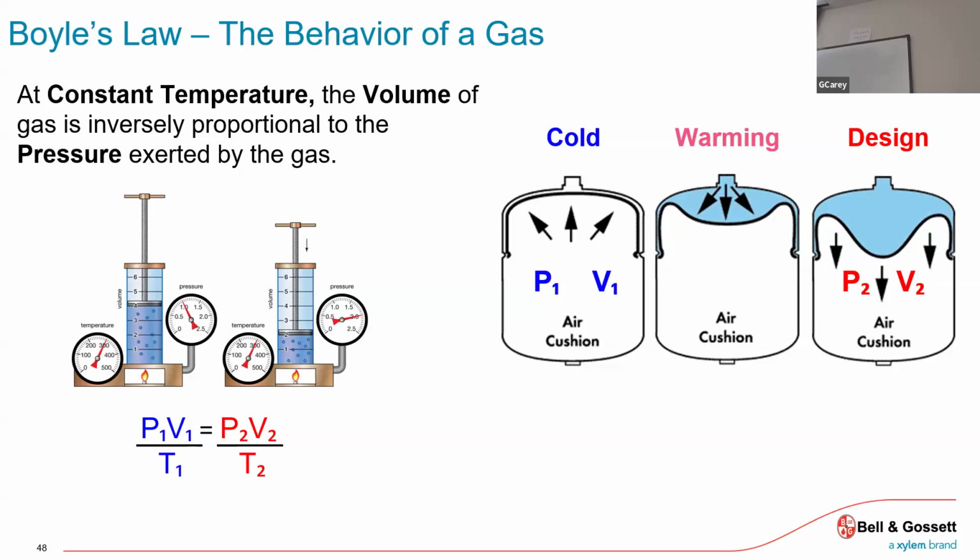But now as the water is heating and it's expanding, it's going to go to the only place it can, because water is not compressible, but a gas is compressible. So I'll squeeze that air. I still have the diaphragm separating the two, but I'm squeezing. So as I'm squeezing, I'm changing the air volume, which means I'm changing the pressure. So the volume's getting a little smaller and the pressure's going up, which is fine. That's its job. The whole key is at the end of the day, as that pressure rises, we just want to make sure we stay below the relief valve setting.